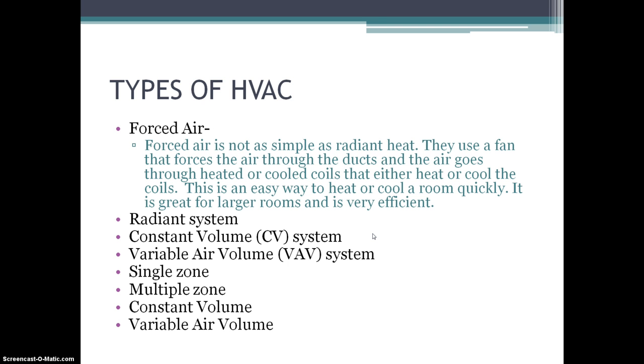So also with that, it incorporates air handlers that are standalone as blower cabinets, and they use a heat pump or a forced air furnace that includes a blower. Also includes a heating unit with a gas-fueled burner or electrical resistance heating elements, ductwork for delivering room air to the heater, and ductwork for sending heated air back to rooms, and a thermostat for turning the system on and off.